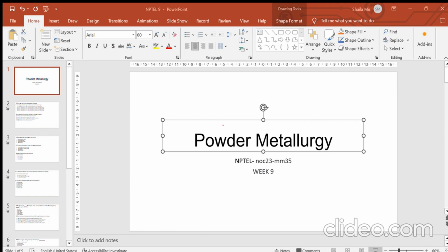So during the sintering process, say you have two particles. They will try to form liquid bridges if it is liquid phase sintering, or they will form solid-solid contact, as in solid state sintering, if these two particles are in contact. So they will form some contacts between one another. What happens actually is that the surface energy associated with these two particles will decrease, because now these surfaces are not available to contribute towards the surface energy. So they interact through solid state interactions, and their surface energy decreases.